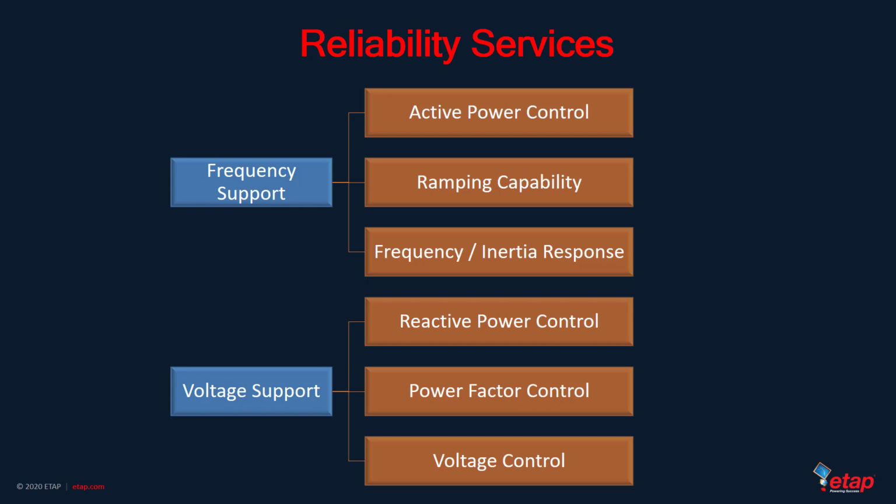Throughout the day, the load on the bulk electrical system will vary. System operators need to balance supply and demand in real time to maintain reliability, adjusting demand from resources throughout the day. The key indicator for measuring the supply-load balance is line frequency. In North America, the electrical system obviously operates at 60 Hz. When demand rises and there is not enough supply to meet it, line frequency goes down. This is commonly referred to as a frequency droop. The tolerance for frequency variation is very small and it's closely regulated.